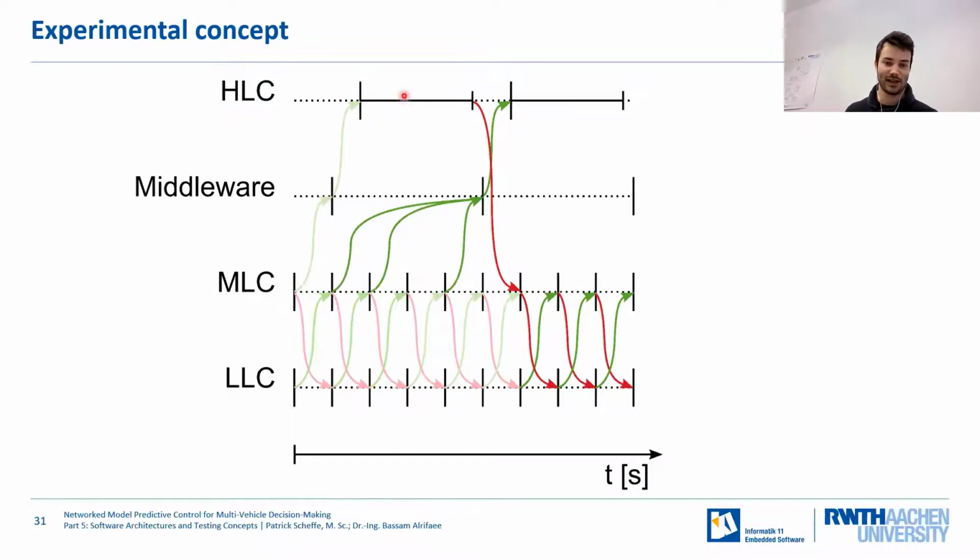So if you know, okay, I need far too long to submit this data, so please just wait until this time or that time. And then the mid-level controller will see, okay, I have new data, but it's not valid yet, and I will just use it whenever I'm told to use it. This way you can negate the effect of varying communication delay and have repeatable, deterministic experiments.